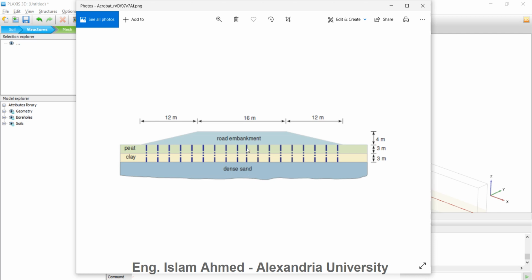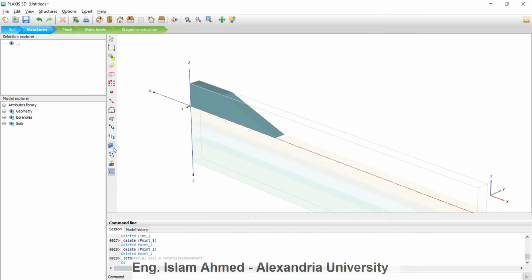So the first sand drain will be here over 1 meter, and for -6, 3 and 3. Create hydraulic condition, keep pressing it, then release, choose the line sand drain 1, and I'm going to construct it here in the middle of the model of these 2 meters.